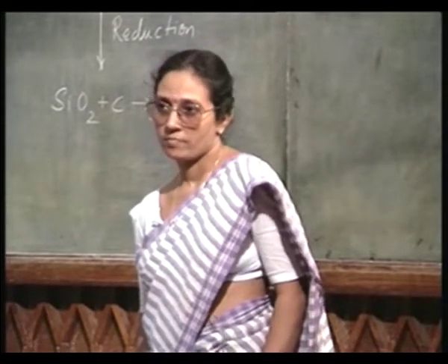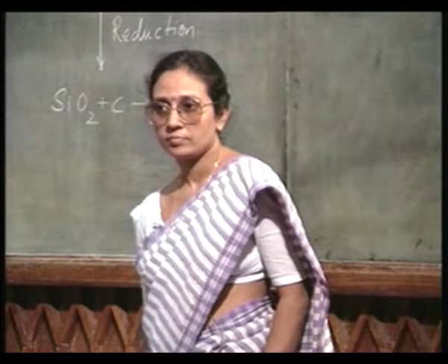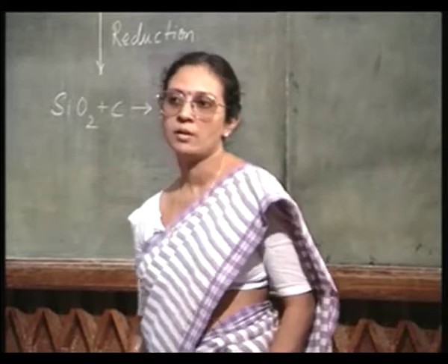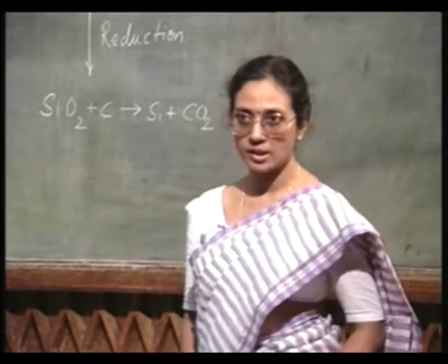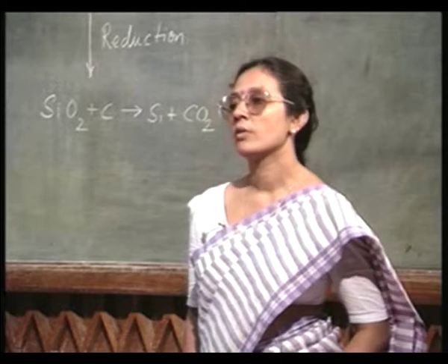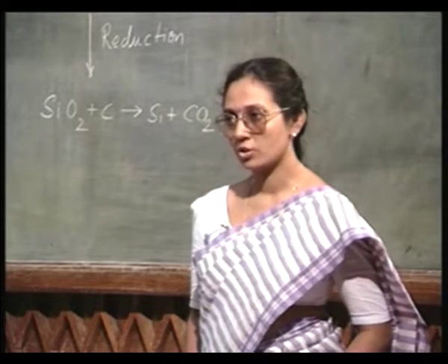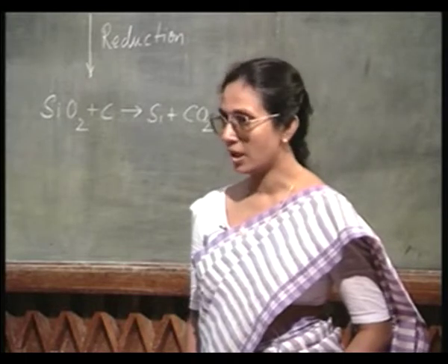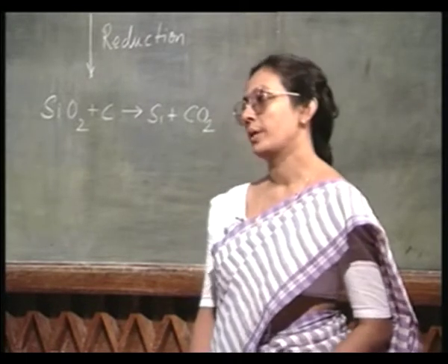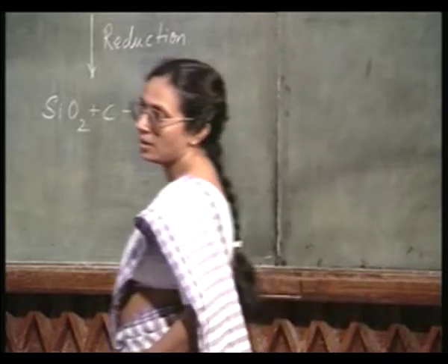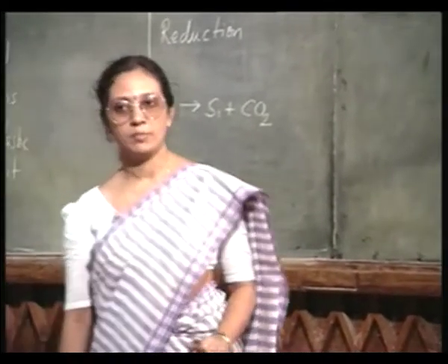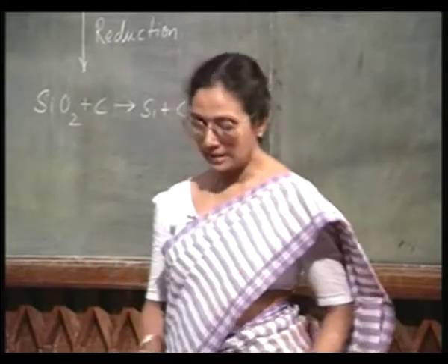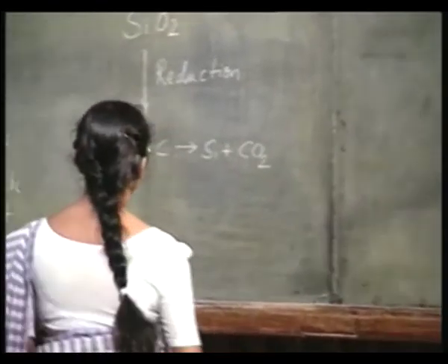You take silicon dioxide, pure silicon dioxide. You have to purify the naturally available silicon dioxide, and then you have to subject it to carbothermic reduction, when you get polycrystalline silicon also of very high purity. Okay. Now that this polycrystalline silicon is available, one has to grow the single crystal, and in this two techniques are used.